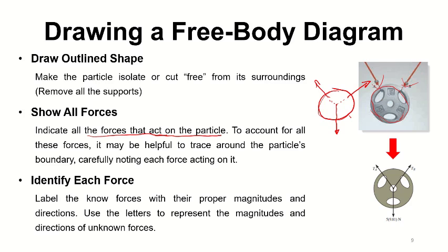Say this is the tension force, I use T, which applies at A, so I use TA. This is a tension force which applies at point B, so I use TB. If the mass of this wheel is 5 kilograms, then the weight is 5 times 9.81, or 5g.